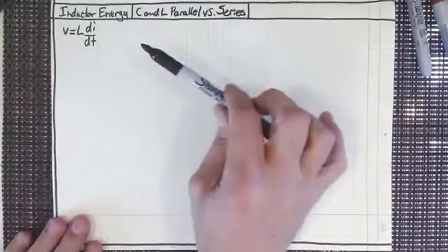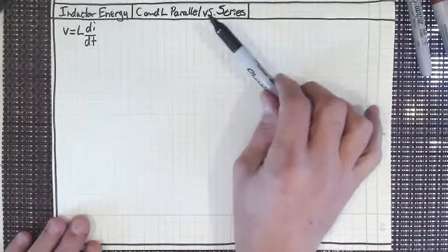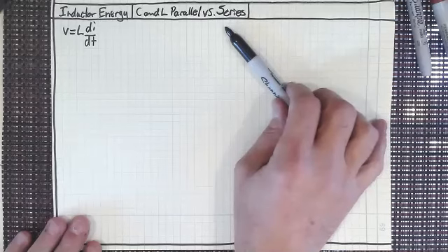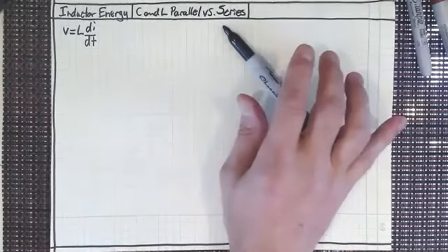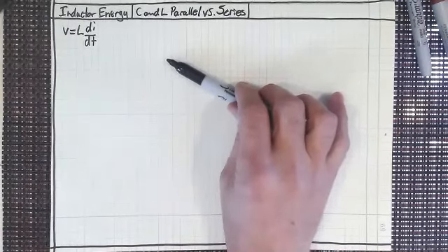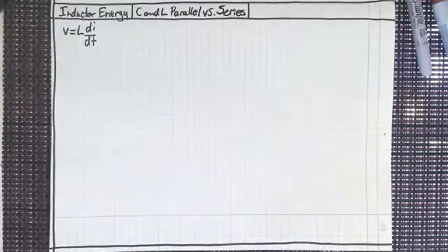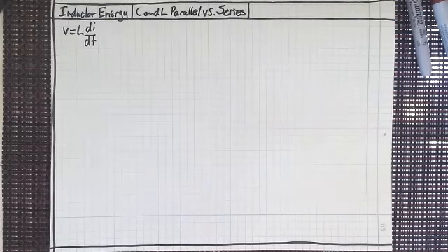One starts as a short circuit. A capacitor starts as a short circuit, ends as an open circuit with DC. I'm qualifying this by saying DC. And for an inductor, it starts as an open circuit and ends as a short circuit. And that should tell you how the current and voltage are going to change in that situation. It's not linear, of course, it's exponential. And we'll look at that when we look at the next chapter, chapter 7. Anyway, so that's one thing.